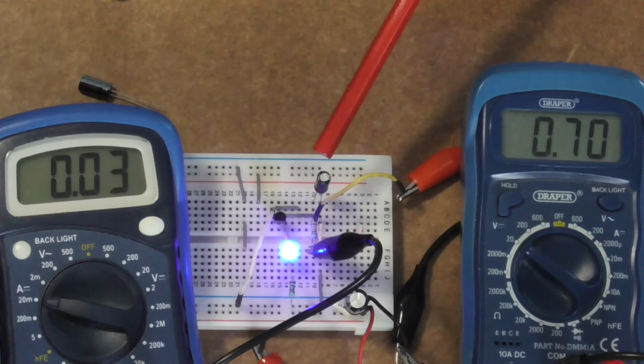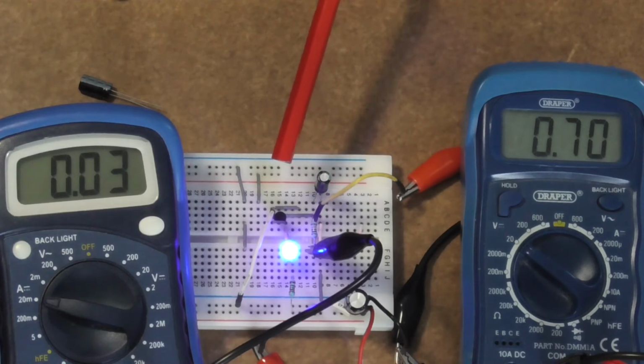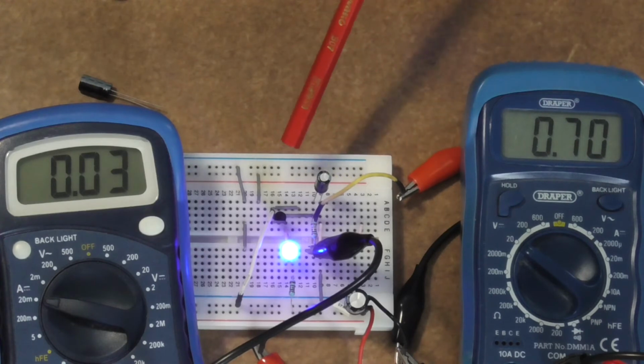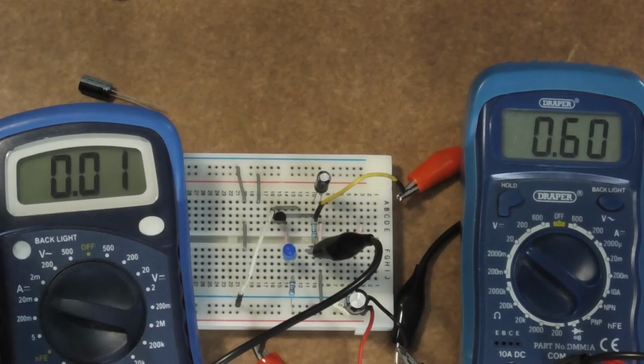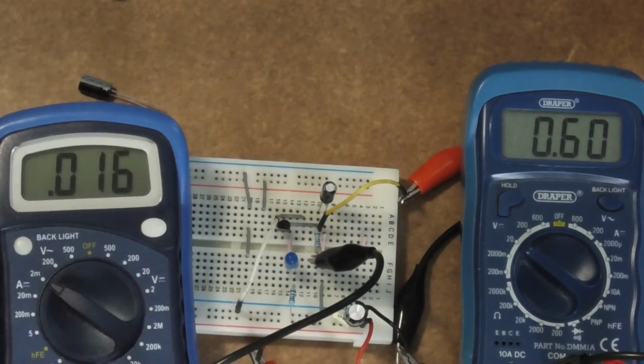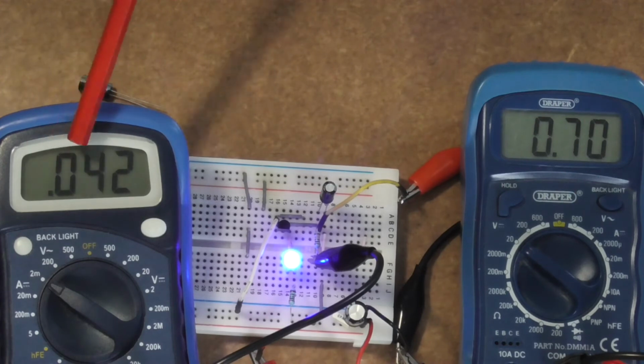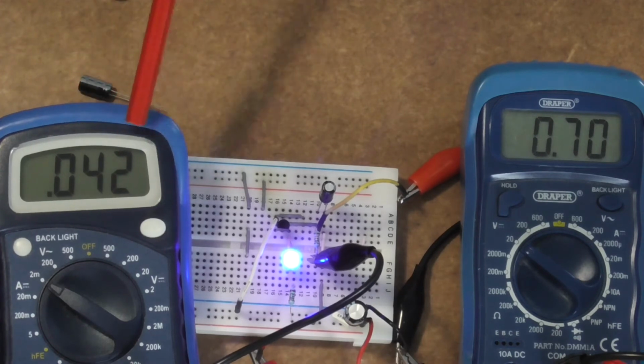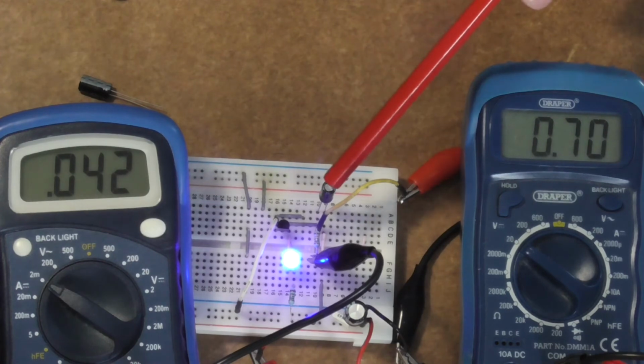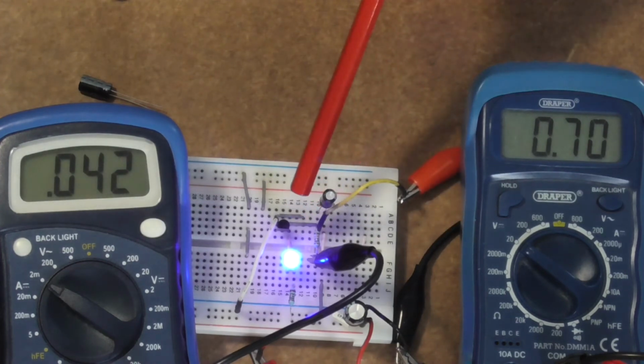See, that didn't come on instantaneously, did it? Actually, look how low that current is, and we've got just enough voltage to turn on the transistor, 0.7 volts. So let's turn that off, go to this upper range. Look at that, we're on the 2 millivolt range, so we've only got 42 microamps on the current, and 0.7 volts. And that did take its time to turn on.